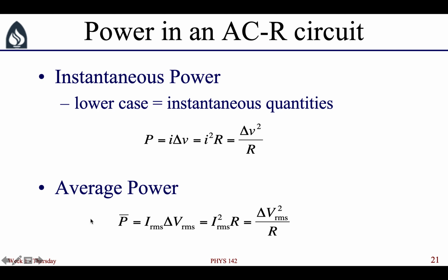If, on the other hand, you want to know the average power consumption, you can use any of these expressions, but with RMS quantities. So using RMS quantities will tell you about the average power consumption for your circuit.